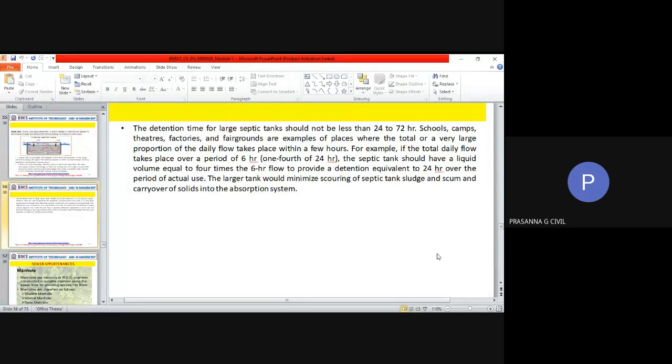The next topic that we have to look at is sewer appurtenances. We have seen pipe appurtenances in the case of water supply system also. Okay, you have seen about sluice valves, gate valves, air relief valves, pressure relief valves, so many types of valves and appurtenances. These are put into place in the system so that the water is able to flow in the pipeline very smoothly without causing any airlocks, blocks and things like that, and in some cases to build up pressure and things. So here we are talking about appurtenances which are put in a sewerage system.